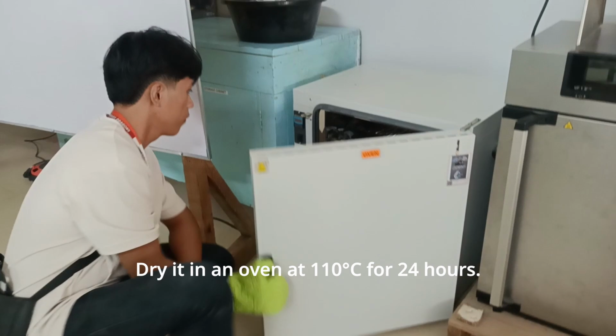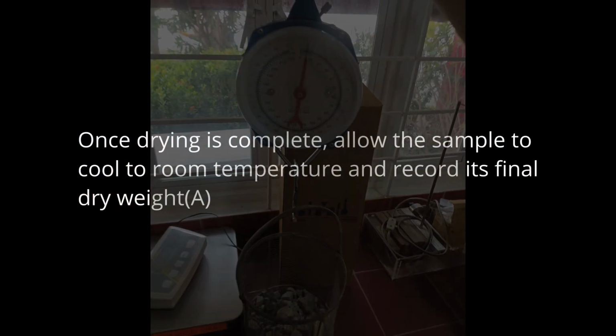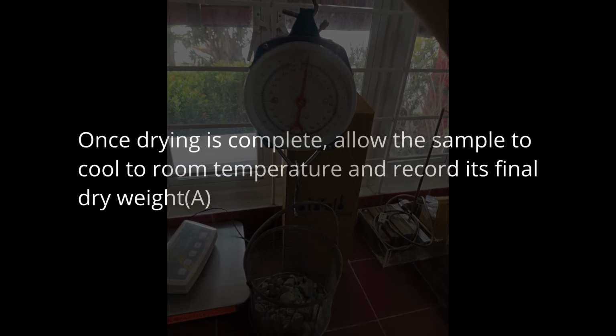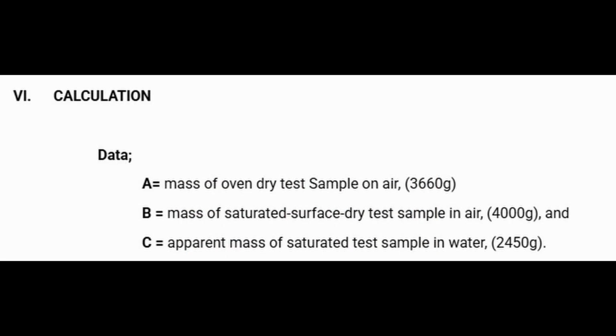Next, transfer the coarse aggregates into a pan and dry it in an oven at 110 degrees Celsius for 24 hours. Once drying is complete, allow the samples to cool to room temperature and record its final dry weight as A. Calculation. So for the data, here is the data we have gathered after the experiment.